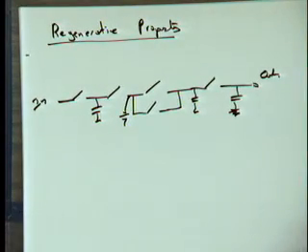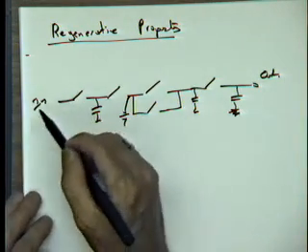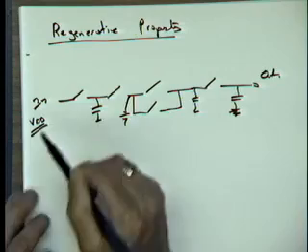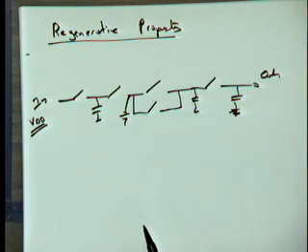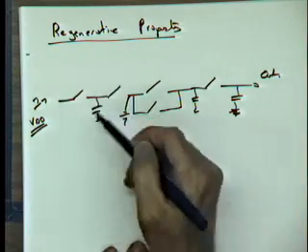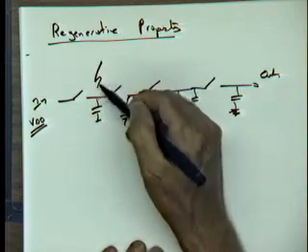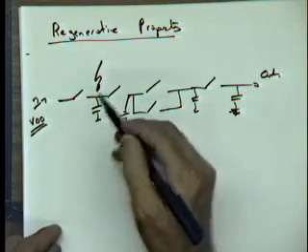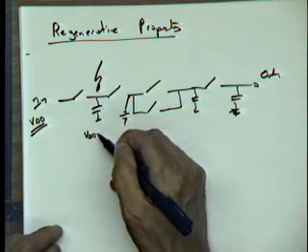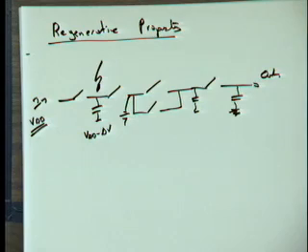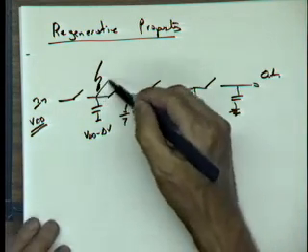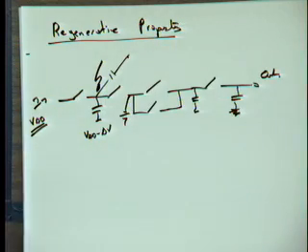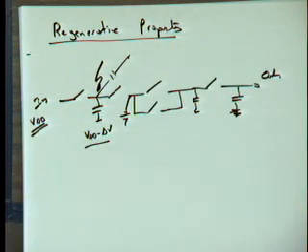Now, if you have a logic family like that, what you see is the following thing. Suppose my input is perfectly fine at VDD. It's a nice, perfect value. But then I have the first switch, I get VDD here, but I add some noise. Some noise comes in. I have some coupling to the neighboring wire. And instead of VDD, I get VDD minus delta V. Okay, I lose some voltage, because of the noise coupling through another capacitor or something like that.